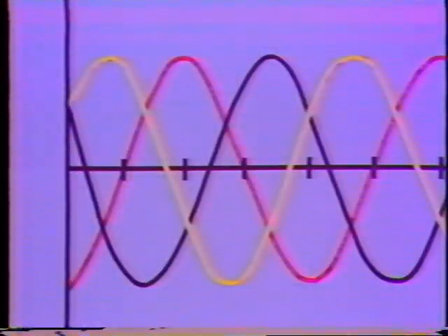So far, we've only been talking about single-phase generators, since all generators operate on the same basic principle. They use a magnetic field, a conductor, and relative motion to produce a voltage. However, the generators in your plant are almost certainly three-phase generators. Instead of one conductor or winding, there are three. This means that you get three output voltages. Instead of one sine wave for each revolution of the rotor, there are three.